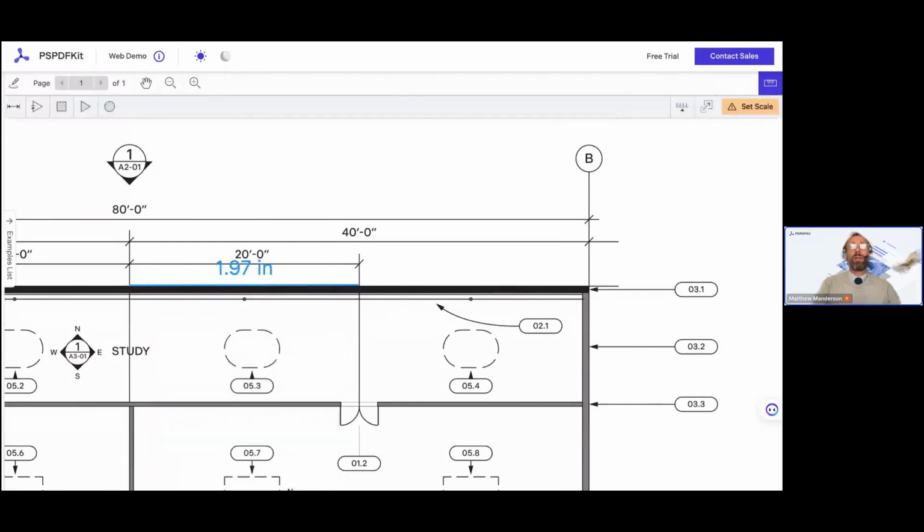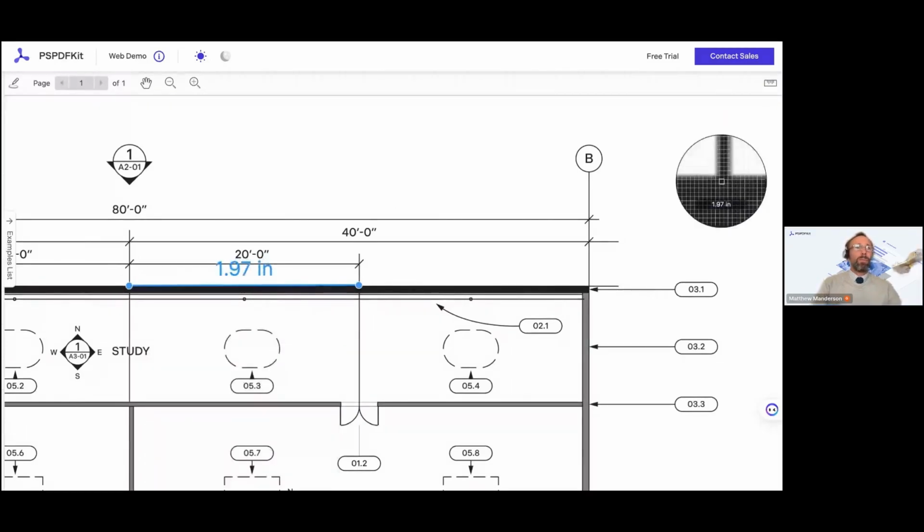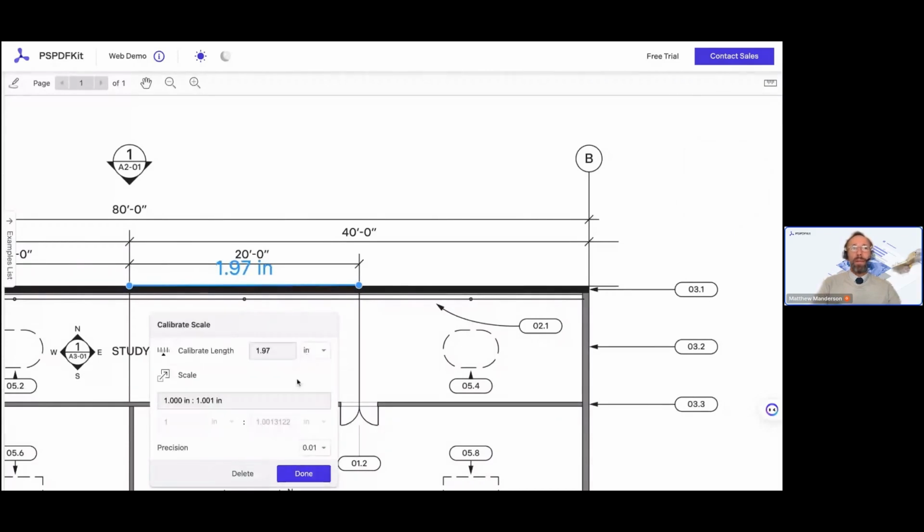And you can see snapping is not in today on the demo. So basically the default at the moment is inches. Now you can set that default per document. As the builder, you can set that yourself. In here, we know that this represents feet, so we're going to change it over to feet, and we know it's supposed to be 20 feet.